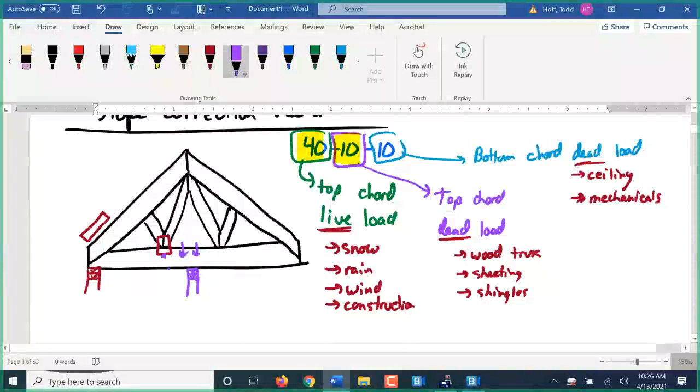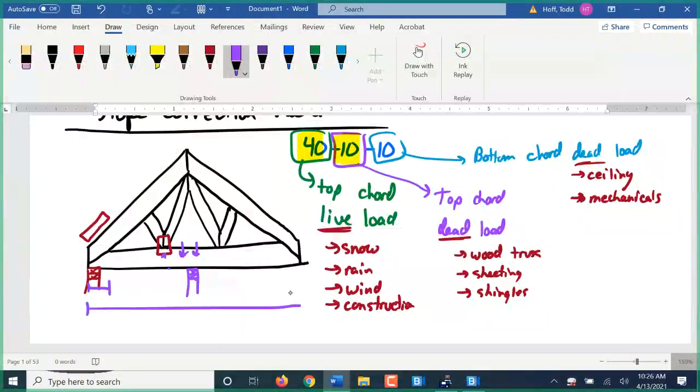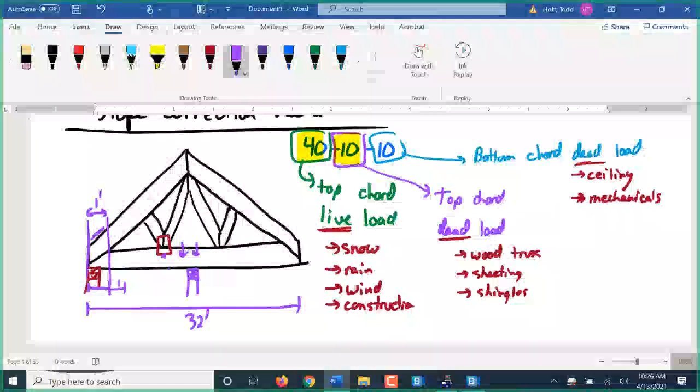So that square foot is 1 foot in and out, 1 foot wide, but it's also 1 foot flat. So if this is a 32-foot span across here, there are 32 1-foot pieces across here, and they get projected up onto the roof. So when we're doing the loading of the roof, this is 1 foot, not going up the slope here. Well, if we have a 4/12, 5/12, 6/12 slope, it's not a significant difference. But when you start getting into higher slope roofs, it is.